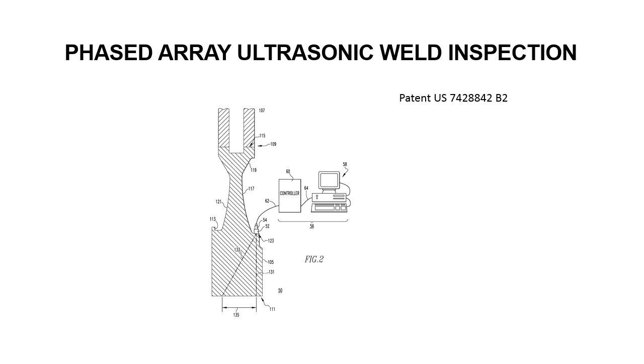Apart from detecting flaws in components, phased array can also be used for wall thickness measurements in conjunction with corrosion testing. Phased array can be used for the following industrial purposes: inspection of welds, thickness measurements, corrosion inspection, and flaw detection.